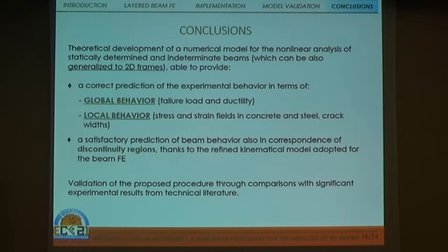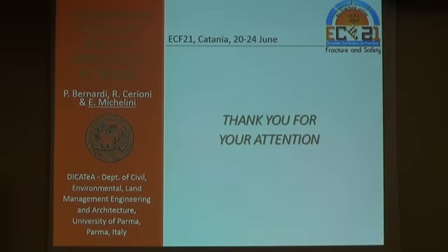So moving to the conclusion, in this work a procedure has been presented which is able to correctly catch the global and local behavior of beams also in the cracked stage. And satisfactory prediction can also be achieved in discontinuity regions where high concentration of stresses occurs, and so also localized failure can be predicted, which can usually be predicted only by using more complex approaches, like for example bi-dimensional finite element analysis. And the procedure can also be generalized to bi-dimensional frames. So I have concluded. Thank you for your attention.